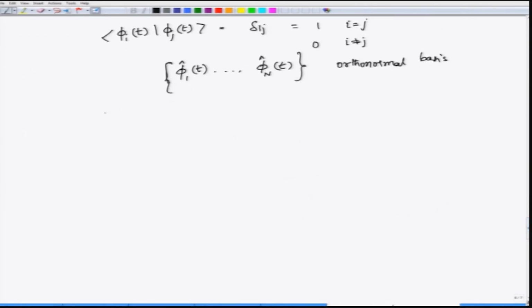What we have found is that any signal sk(t), which is a time duration waveform, can be uniquely represented or specified by giving its components ski. What are these ski? They are obtained by taking the signal sk(t) and forming the inner product of this with the ith basis function. So, this would be ski, and the set of ski, how many should I have for each k?